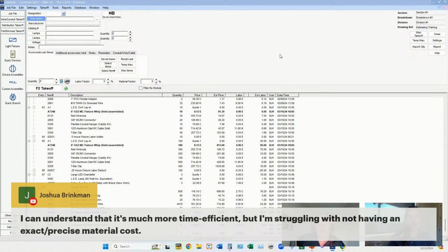But I think that's a really good shortcut, to take half of the longest distance in the building. If you stop and think about it, what's the average home run going to be? It doesn't matter where the panels are, the average distance from any location back to the panel is going to be half the distance of the building. Sometimes it'll be 10 foot if it's 100-foot wide. Sometimes it'll be 90, but it's going to average in the middle.